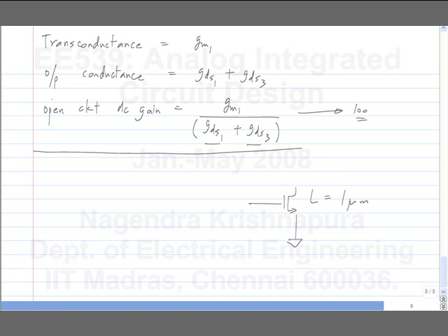And then I'll adjust it to the overdrive with which I intend to operate in the given scenario, something like 150 or 200 millivolts. And then I simulate the GDS once. Once I know that, I'll know whether to increase or decrease the length, where to stop, etc. Although, given lambda, you can calculate it in closed form, it's not very useful. In fact, the way I would calculate lambda is by simulating a transistor and looking at the value of lambda. Lambda is not something that's given to you by the process. It's a combination of different parameters because of different phenomena that happen in the MOSFET.